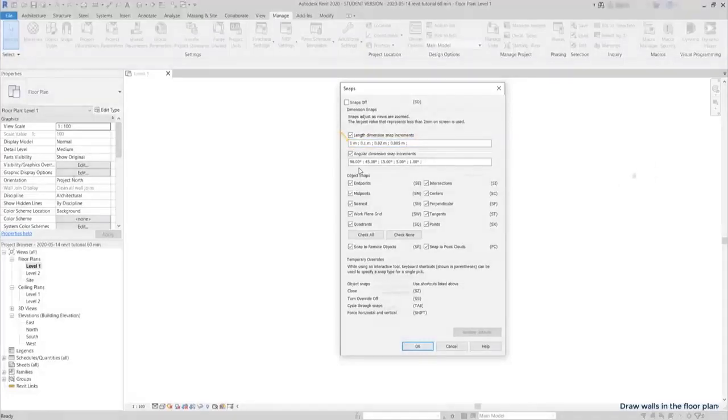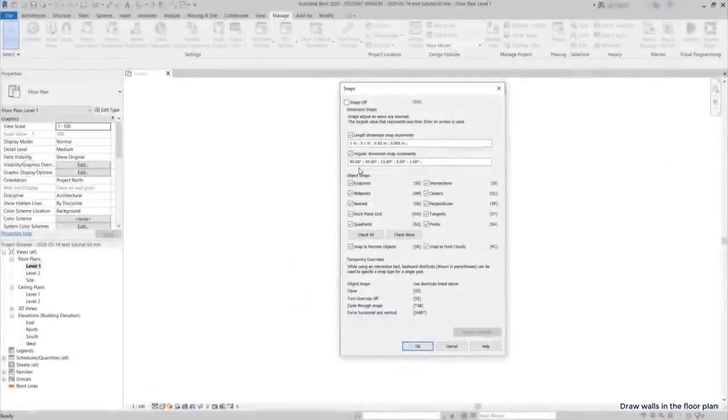The first value is when I am at a minimum zoom. The ranges are in the meter. At a certain point, it snaps every 0.1 meters and so on. I'm going to change it in order to have just 3 ranges and the last one 0.01.